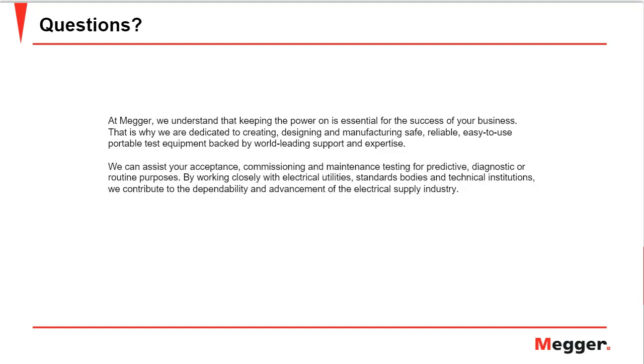So negative sequence overcurrent is not used that often for transformer protection, but there are some applications where it is being used. Basically, negative sequence overcurrent is more sensitive to phase-to-phase faults compared with the regular phase overcurrent elements. So the way you set a negative sequence overcurrent is the same way you would set a phase overcurrent element, by doing some coordination analysis.